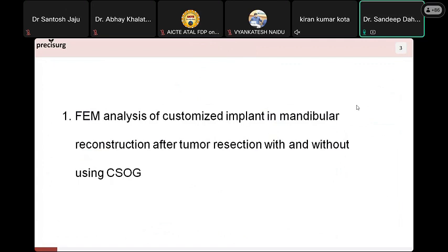For performing the finite element analysis, before selecting the mesh size, we performed the mesh convergence test. This test is important before selecting the mesh size, so that we can check the time required for the finite element analysis, and any errors that happen can be sorted out.